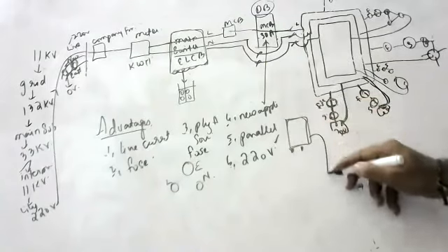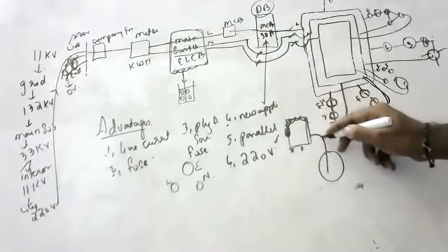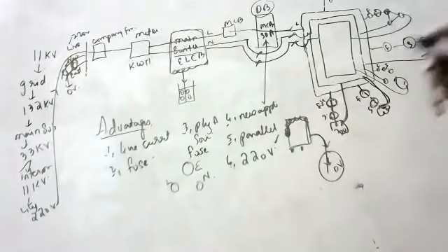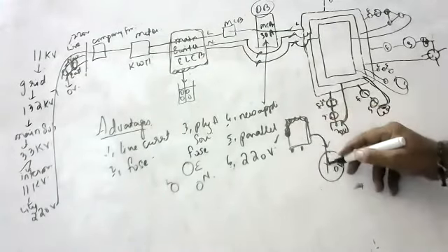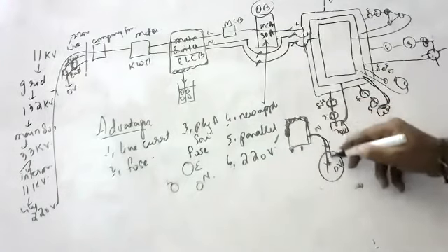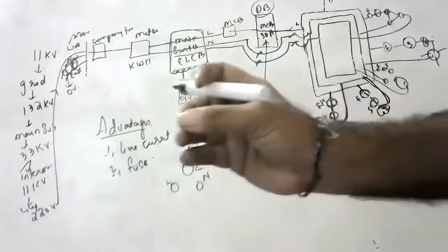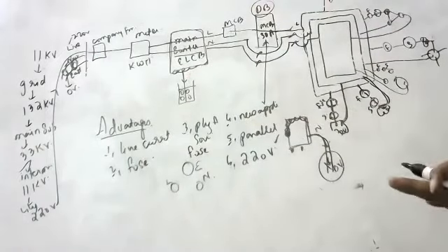So if you put one earth wire, if ever any disturbance is there in the fridge, all the excess current will go to the earth. Why will it go to earth? Because earth is also maintained at 0 volt potential, like the neutral wire. So all the excess current will go to earth and the user will not get a fatal shock, just a slight shock. Immediately he will call a technician and the technician will check all those things.